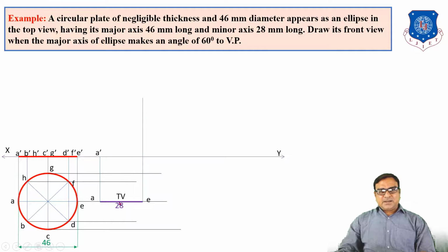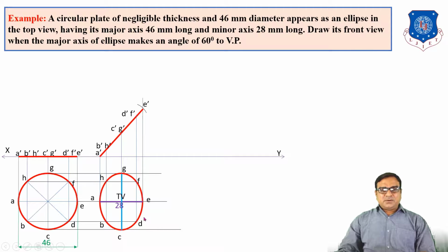Take the length AE as radius, with A dash as center, draw an arc at A dash. Insert the remaining points and draw verticals from all points. You will get the other points B, C, D, E, F also. Now trace a curve passing through all the points.